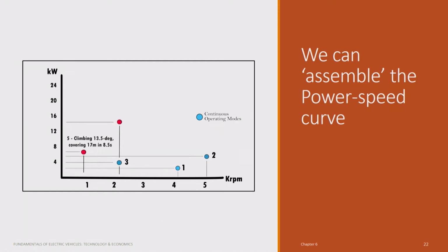and it is not only the power that matters but the speed at which you get the power. So unless you describe the combination of power versus speed or torque versus speed, you are not really describing the motor properly. Just by saying, oh, this is a 3.5 kilowatt motor, tells you nothing about the motor. Fine.